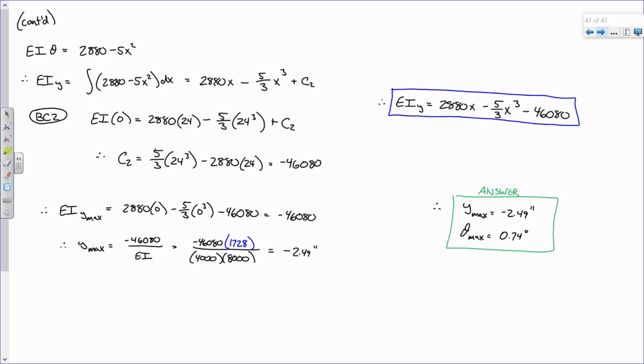So the obvious answer in a floor beam system is let's take this room. There's a column right there, and there's a column right there. So these floor beams have to hold up all the load halfway over to the next floor beam and halfway over to the next floor beam. Just put another floor beam in. That beam is responsible for less load, so it doesn't have to be as big.